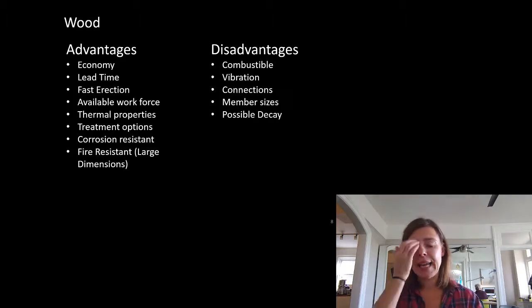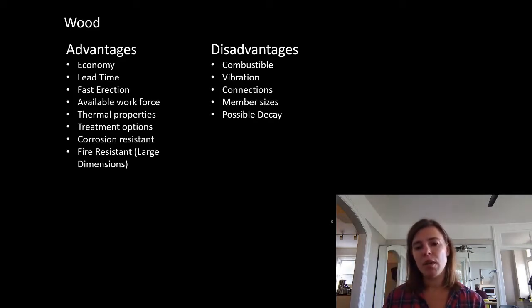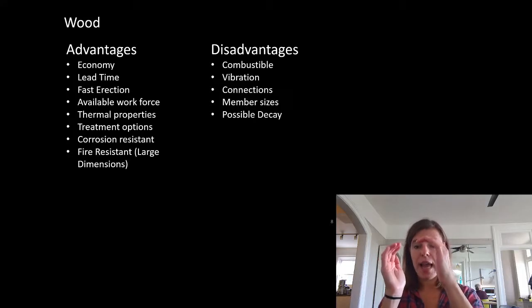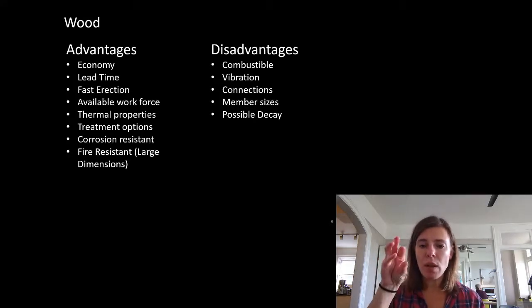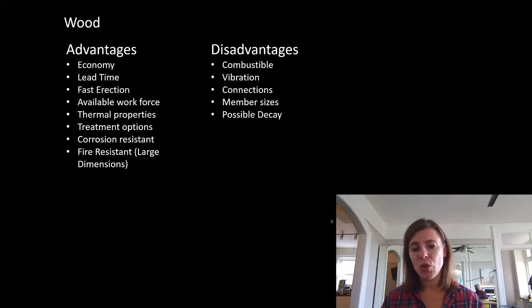The second thing, the reason that doesn't work on small scale elements, is that as it burns away, if you only have a small element, you've burnt all the way down into the middle of it. So a 2x4, if it's going to char an inch around the outside and it's only 1.5 by 3.5, you're left with no structural material after that 1 hour burn.